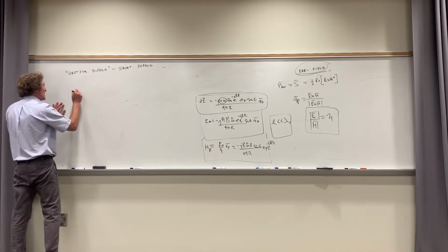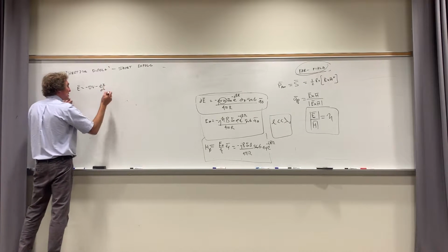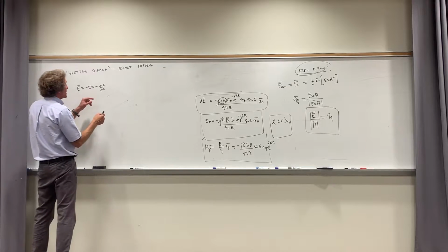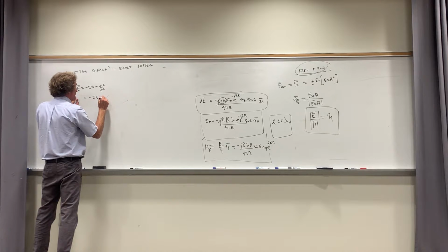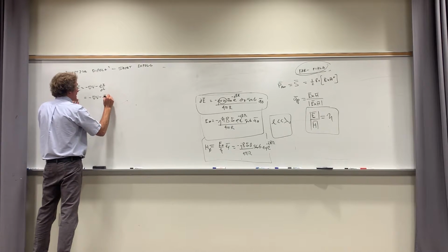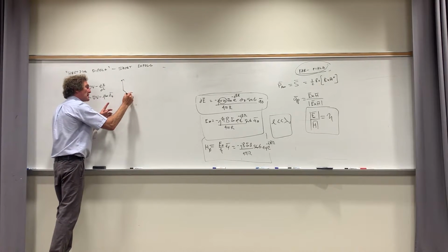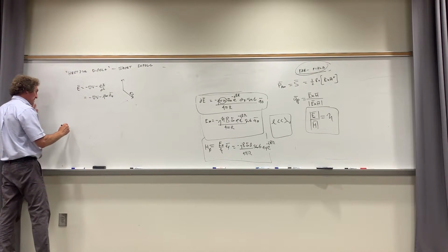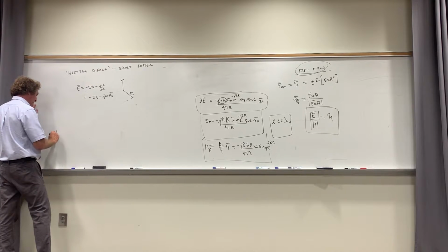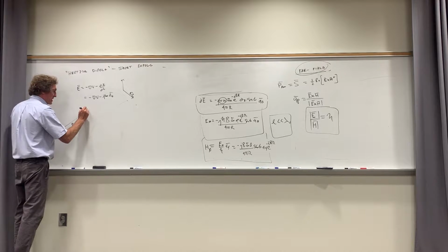Here's why. When I put E equal to minus the gradient of the voltage minus dA/dt, this is going to be minus the gradient of V minus, and this becomes minus j omega times the A_z vector. But remember, A_z is pointed this way, E theta is pointed this way, and what you're really doing is this. If this is I dl here, and I'm a distance r away, and my vector is this way, this is A_z.